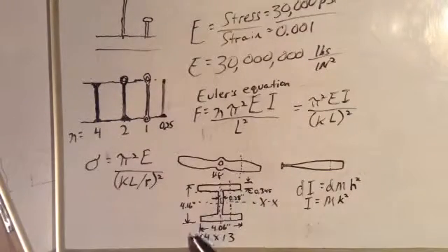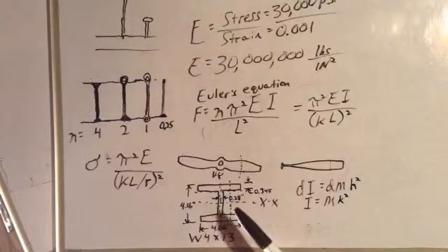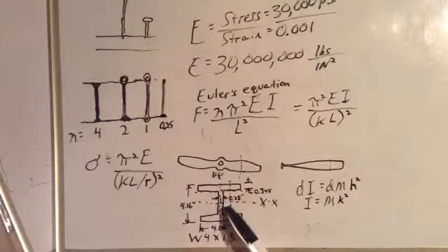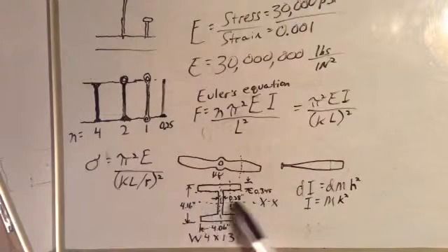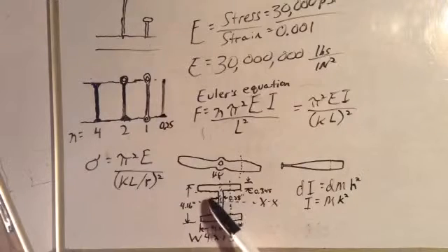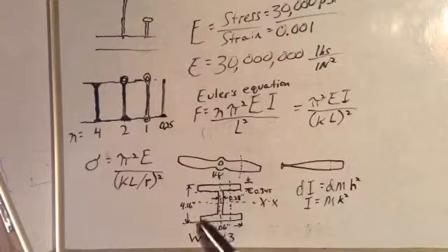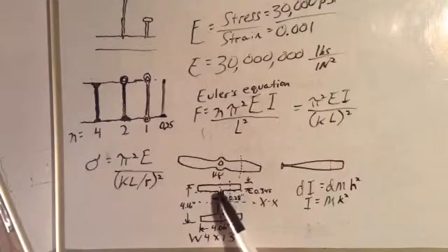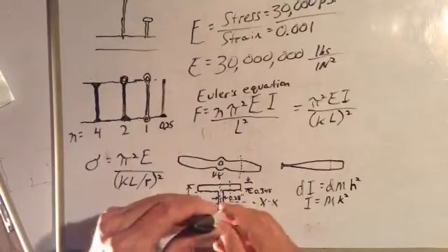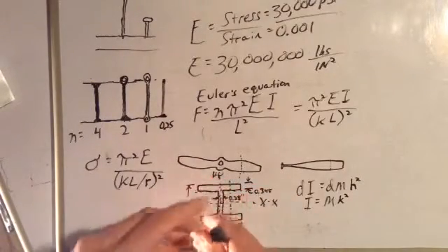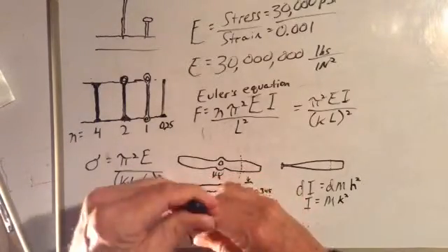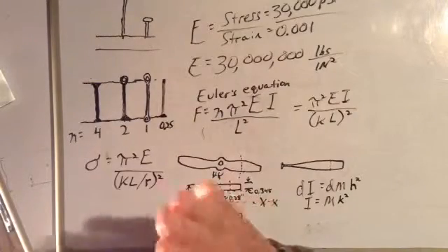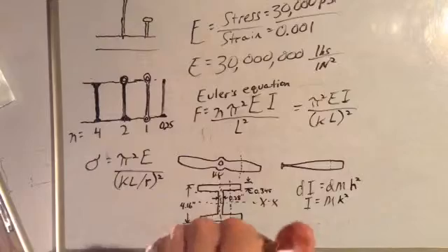So anyway, this is 4.06 inches across, so it'd be 2.03 inches from the center of this eye to here. And the radius of gyration is just a little less than that. It's 1.004 inches. But looking across this x-axis, our radius of gyration is 1.7 inches because we have so much area up here and so much area down here. So the weakest axis, this beam will buckle, like if we were looking at it, it'll buckle this way or this way. It won't buckle that way or like that. It's going to fold over like that or that, not that or that.